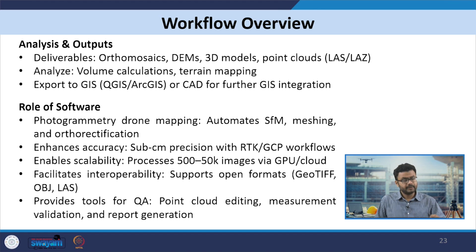So here the main deliverables that we expect from such software are orthomosaic, digital elevation model, 3D models, and also point cloud. And we can do analysis in the form of volume calculations and terrain mapping. We can also export to GIS software, for example for use in QGIS or ArcGIS, or we can export as an object file to be used in CAD software.